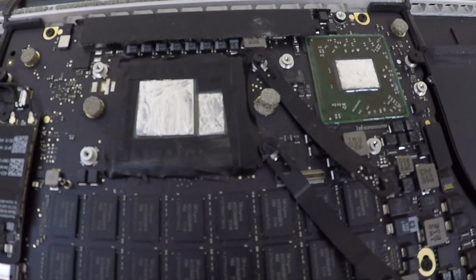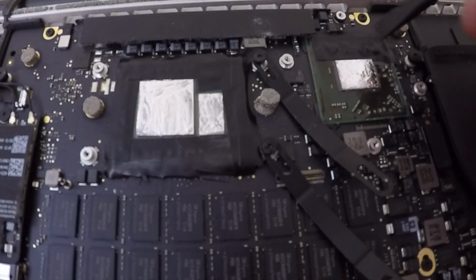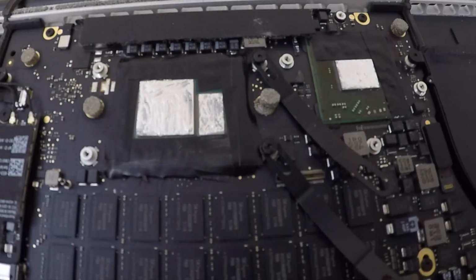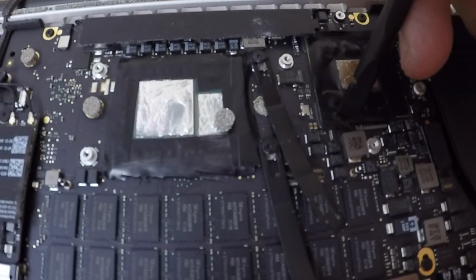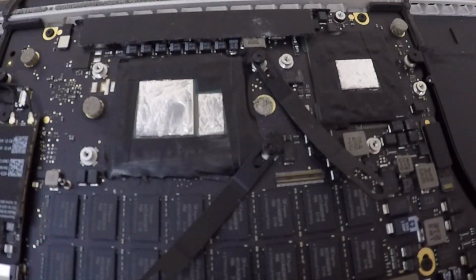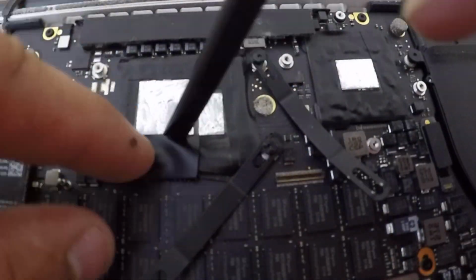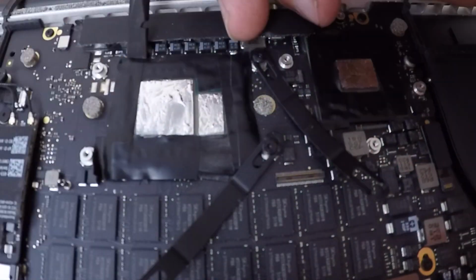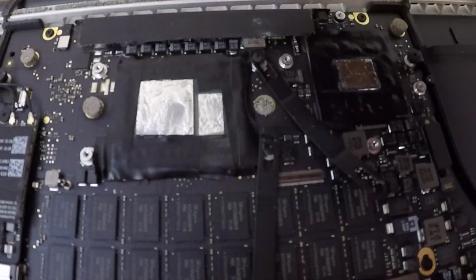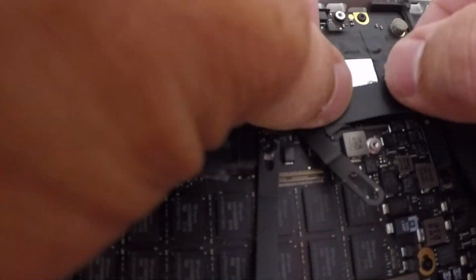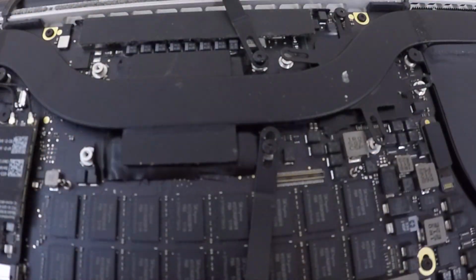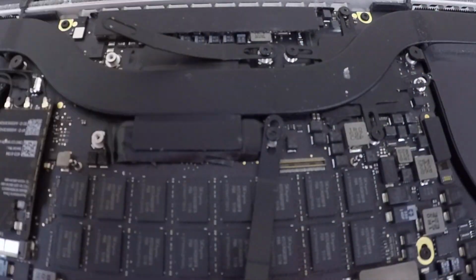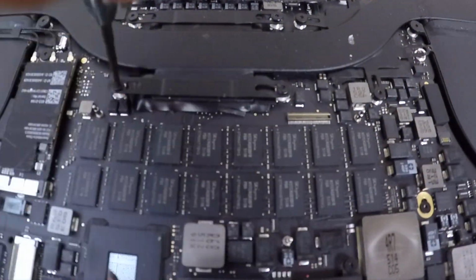So I had to do another video, and I'm actually going to take everything apart again and show you what the liquid metal looks like afterwards and see if I had enough, and also see what happened to the tape, because I was quite concerned about what the tape did. Now after you get all your tape on the CPU and GPU, you're going to put the heatsink back on it and make sure that you get it lined up perfectly straight, and then push down on it and apply the screws to connect everything back together.